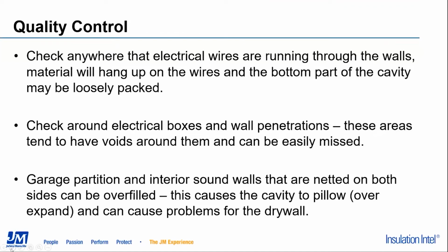Garage partitions and interior sound walls that are netted on both sides can be overfilled. We want to be cautious and make sure that we do not pillow or overfill the cavity and cause problems for the drywall crew later.